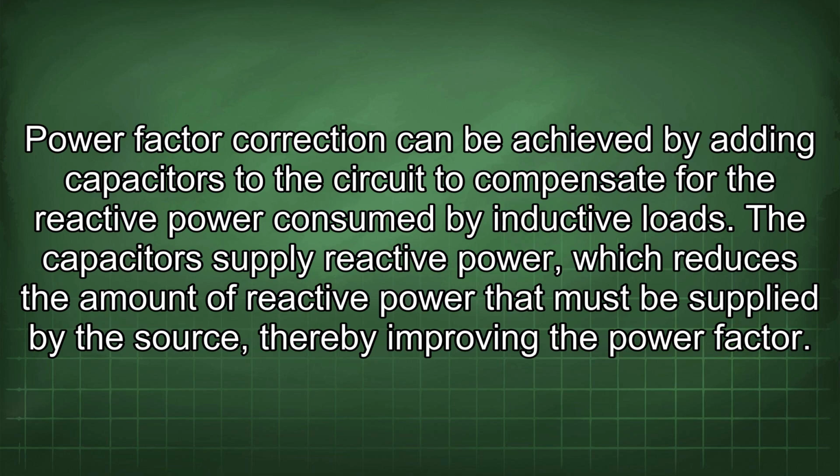Power factor correction can be achieved by adding capacitors to the circuit to compensate for the reactive power consumed by inductive loads. The capacitors supply reactive power, which reduces the amount of reactive power that must be supplied by the source, thereby improving the power factor.